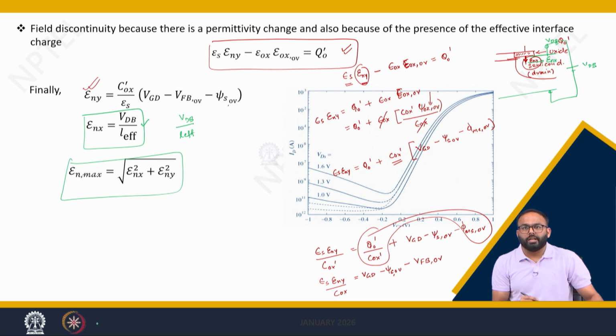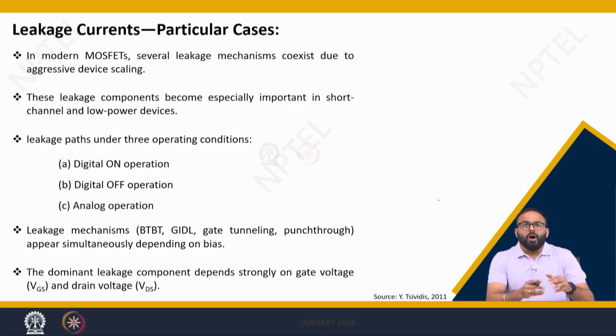If we plot the GIDL current, it is clear that due to the GIDL effect the off current, or the leakage current, increases. You see, if you increase VDS, the GIDL current component increases, and that is a reverse current, right, if we plot against VGS on this scale. So, let us see what are the possible leakage currents we have discussed so far and how they show up in our MOSFET operation. To understand all the possible leakage currents which we have seen in short channel devices,